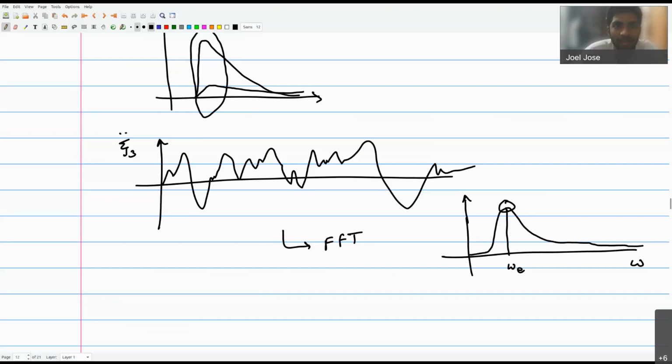So that's basically like RAO times the wave elevation. Yeah, I don't care about the amplitude. No, I'm only interested in finding out the frequency. So the wave will also be of the same encounter frequency as the response is, right? But that will be actually a product of the RAO as well as the. Correct. That's right. In fact, this will be omega square times the product of the RAO times the wave amplitude. But I don't really care about the amplitude. Okay, yeah, I'm just interested in where the peak is, yes. So that I can just get the encounter frequency out of it. Yeah, I think I got it.